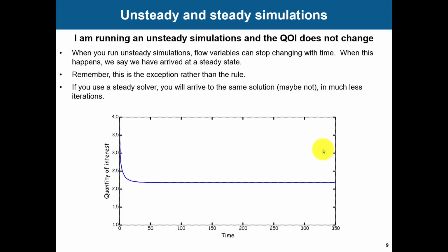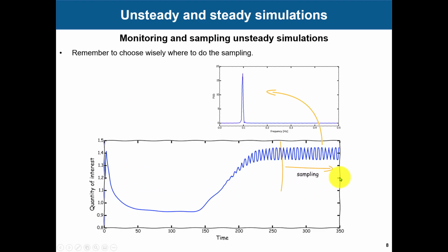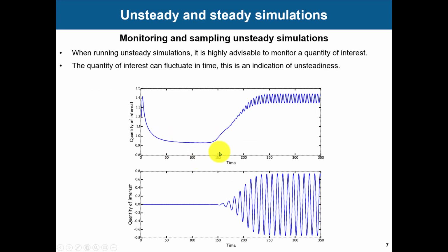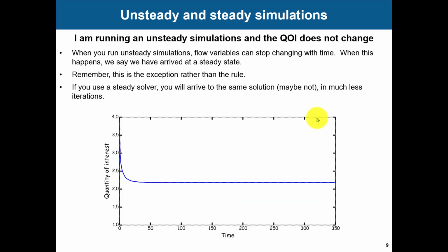And what will happen is you are running unsteady simulations and you actually see this behavior. So see here that we let it run 315 seconds. Here it was just after 150 that you have a set. By the way, this is the same problem, the cylinder problem that we were running, but at a lower Reynolds number, so you can try this. So what will happen is you see this. It means that you have reached a steady solution. Here we're running a Reynolds number of 20. We know that there we don't have the onset of the von Karman street, and this is the behavior.